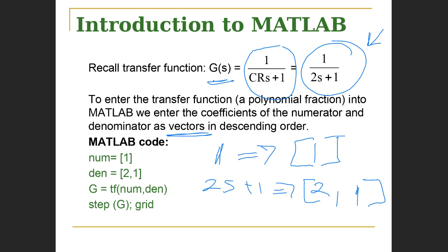Let's put num; you could call it any symbol you want, I could put n, it doesn't matter, as long as you use non-reserved terms, I mean terms that are not dedicated for specific operations in MATLAB. So coming to MATLAB, we have num, and we're using some special MATLAB features now.